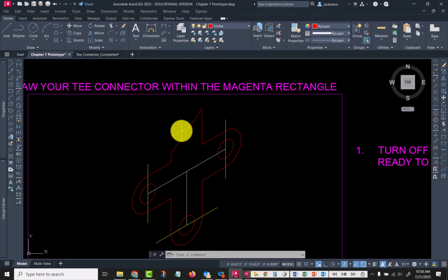So now we're going to create the fillets and the rounds, which you have to use an isometric ellipse to do. And so the book tells us to create some construction lines 0.387 of an inch away from the inside corners. And so let's go offset.